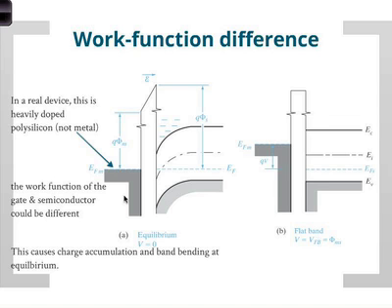Now, the reason you don't use metals is because metals are important impurities for silicon. So you cannot put gold there, for instance, because gold will diffuse into silicon and mess with its doping properties. So in most CMOS fabrication plants, you actually use a polysilicon gate, very heavily doped. You put in enough dopant so that the conductivity is so high it's almost like a metal. So the work function here is typically some phi m, but that will be different than that for the doped silicon.